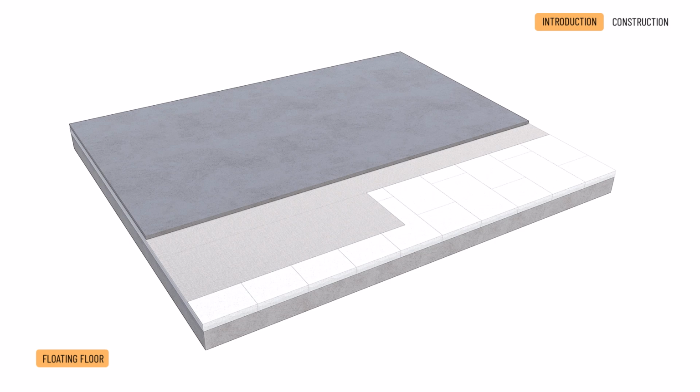The built-in thermal insulation layer can serve multiple functions simultaneously. For intermediate floors, it provides impact sound insulation. For floors on grade, the thermal insulation function is more important, and the layer thickness is designed accordingly. In addition, other layers may be present in floor structural layers, such as waterproofing against service water in facilities, separating membranes, or sheet drains that function as a drainage system.